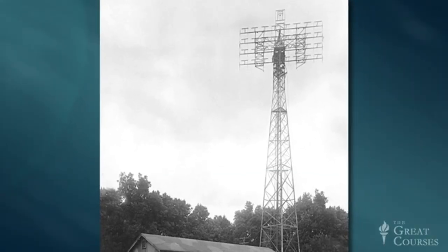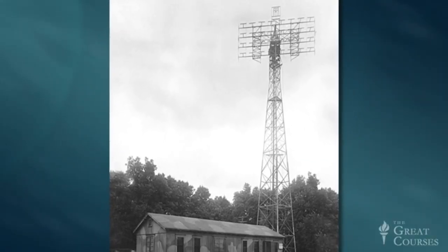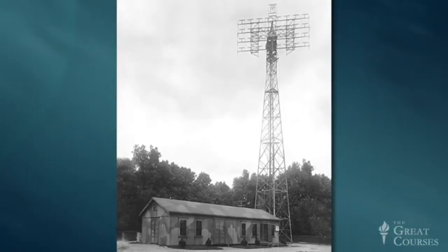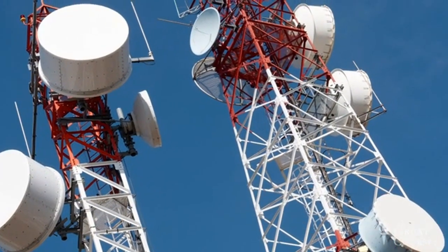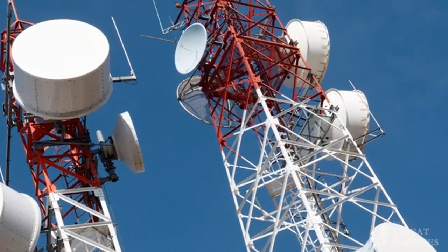Still, the use of coax is severely constrained by the need for amplifiers spaced at roughly 1.5-mile intervals along the transmission lines. This limitation led to a new technology, microwave communications, developed originally for military applications during World War II, and subsequently deployed into the core of the PSTN as a replacement for coax on long-distance trunks. A microwave is a form of electromagnetic radiation, a very high-frequency radio wave, which can be focused into a narrow beam and used for point-to-point communication.